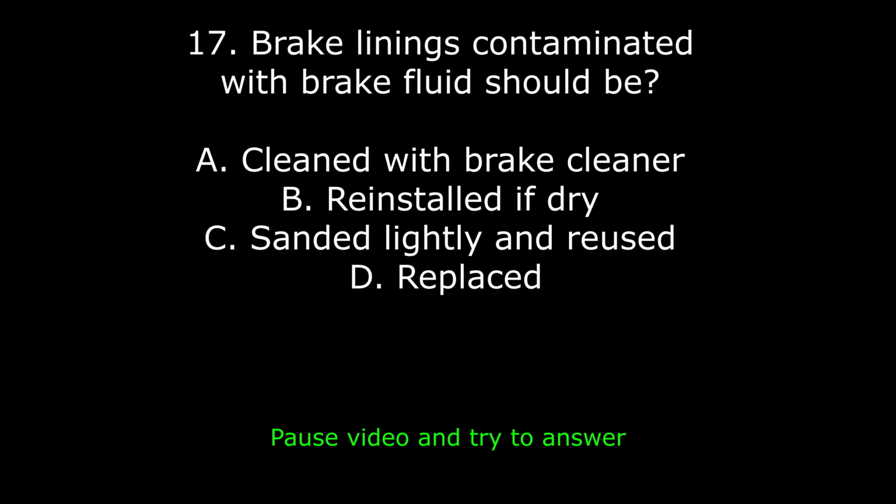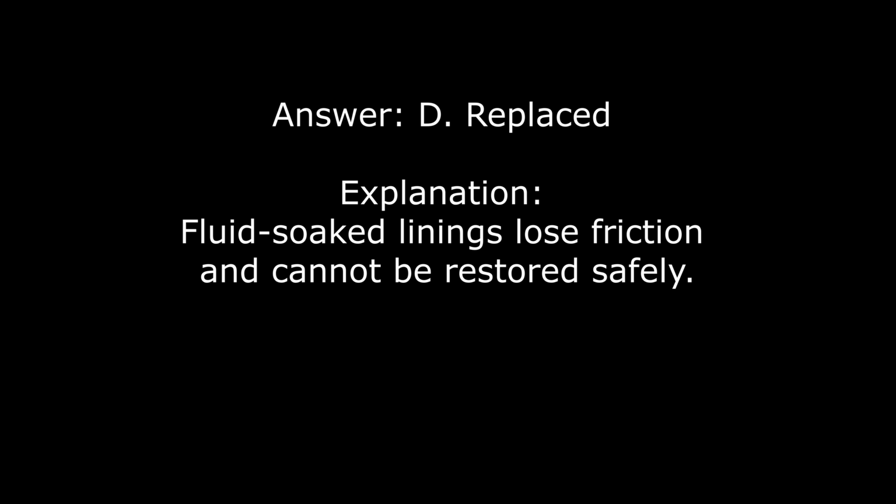17. Brake linings contaminated with brake fluid should be A. Cleaned with brake cleaner. B. Reinstalled if dry. C. Sanded lightly and reused. D. Replaced. Answer. D. Replaced. Explanation. Fluid-soaked linings lose friction and cannot be restored safely.